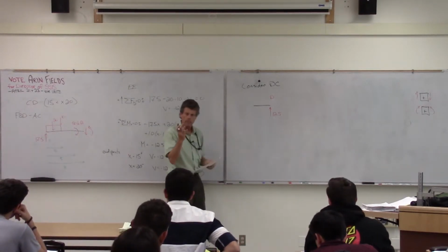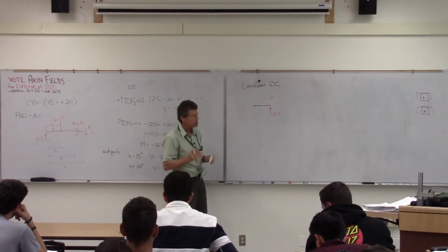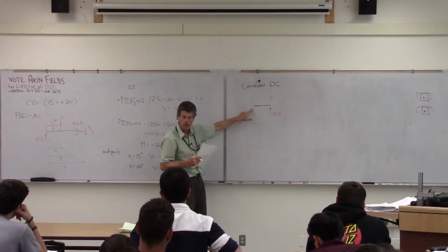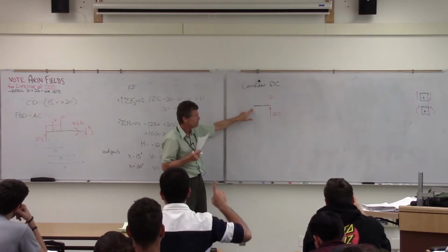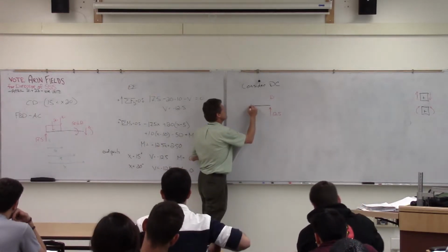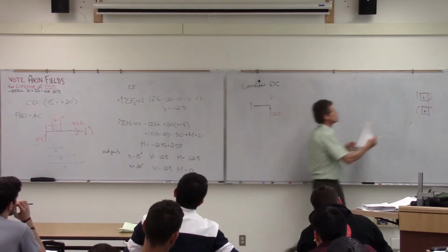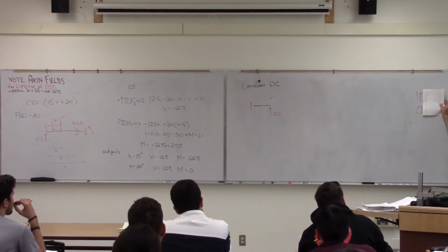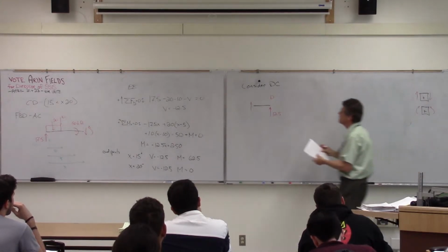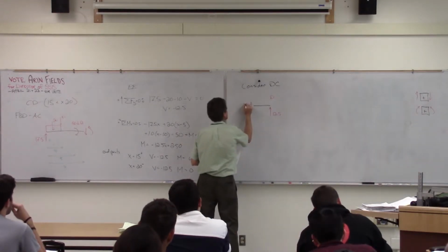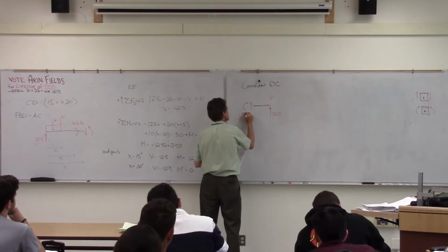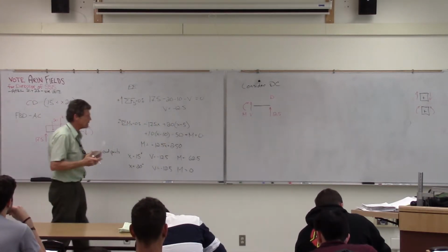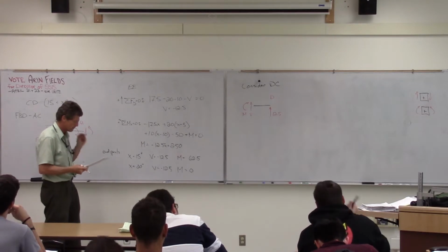When I put in my positive quantities, which way should my positive direction for shear be when I make this cut? Up. Good. You guys remembered. We're going to use this side of the positive convention. So we're doing Newton's third law there. And the same thing with the moment. It's going to be a twist in the opposite sense. So again, that's just the positive quantities. If they solve as negative, we'll show them as negative.